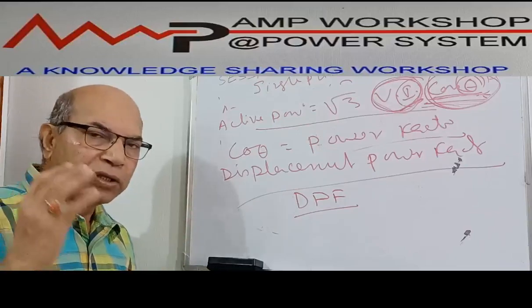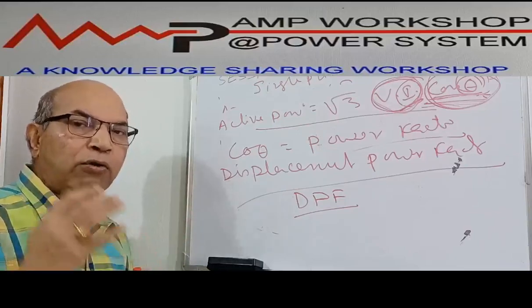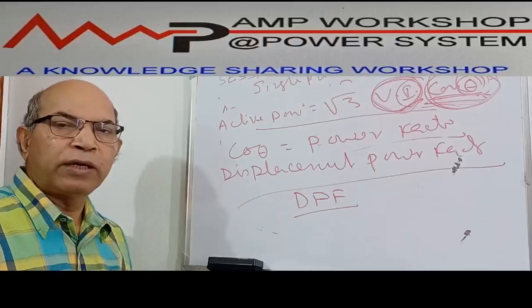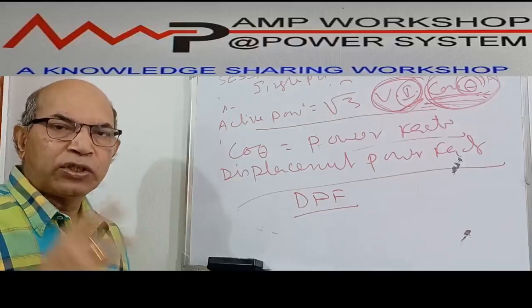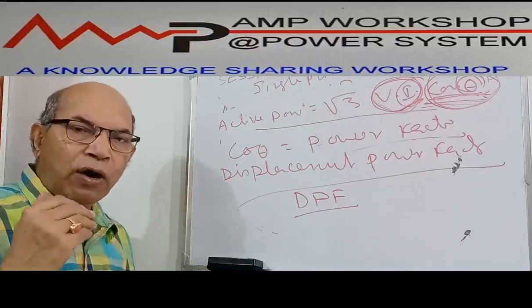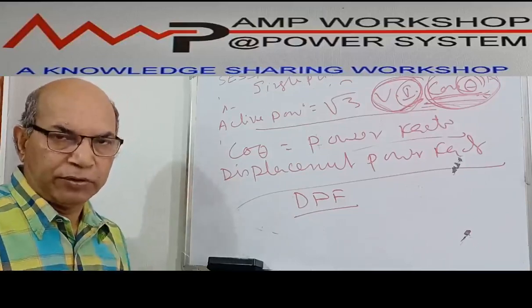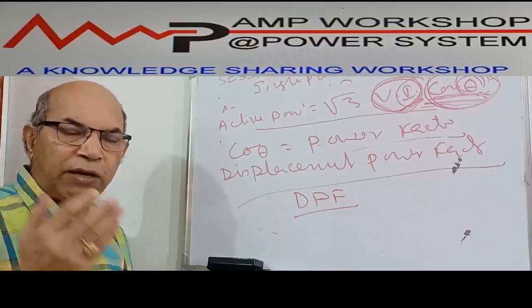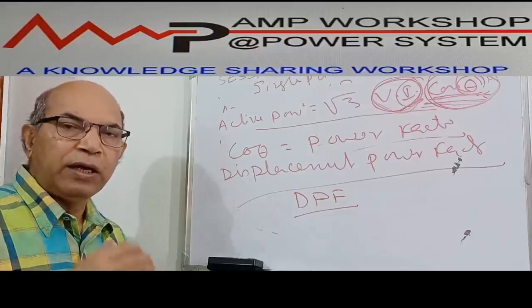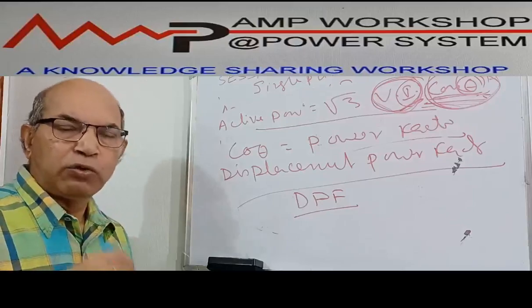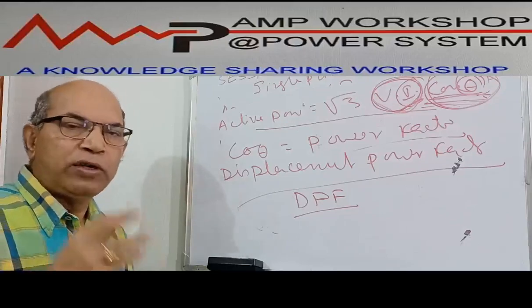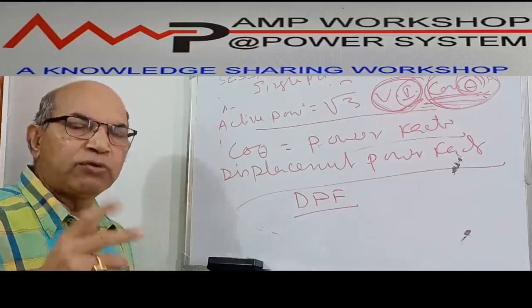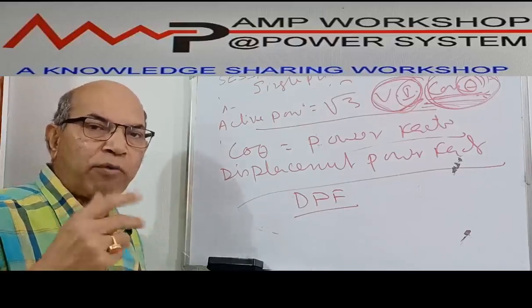Now any circuit which contains a non-linear load, what is a non-linear load? Like a fluorescent lamp or arc lamp, which is continually switching on and off, or welding transformers, which draw high current with sparking. Then it could be a converter, an inverter, a soft starter, or a variable frequency drive, which has solid state devices continuously switching on and off.